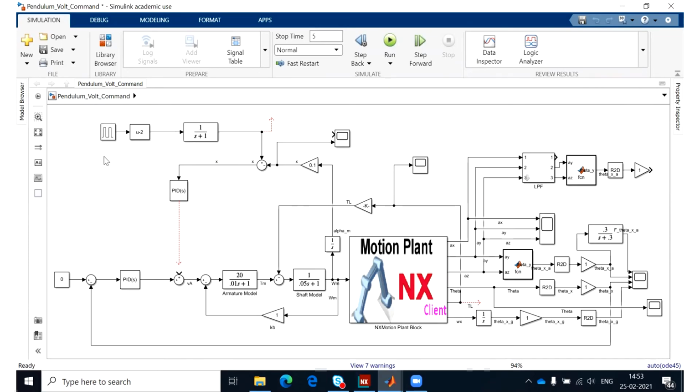In the second control loop, we subtract the displacement of the Segway from the desired position you have for the Segway, and then you use another PD controller. How to design these two PD controllers? Basically, the approach we have is the state space approach. So we model the system in the state space and design a controller in that domain. But later you will see that whatever you have designed in the state space can be interpreted as two PD controllers, as I have shown here.